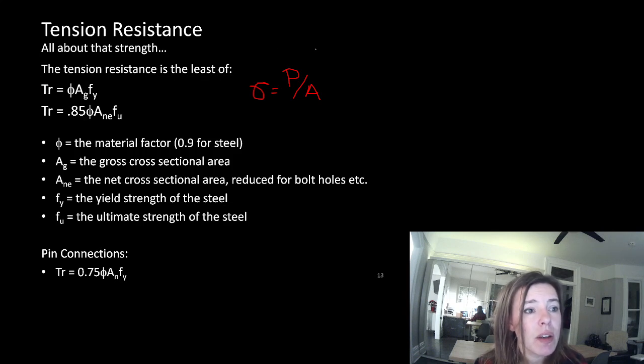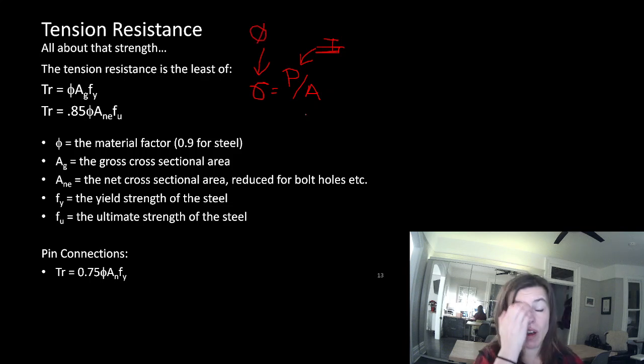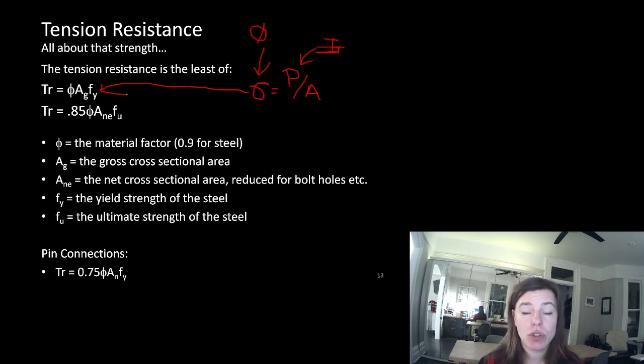TR is, we've just said, we're talking about a force that is T. We get to use the subscript R because we are talking about this having a reduction factor on it. So remember, when we talk about a reduction factor being applied, we get to start using the subscript R. At stress, we know we're a little bit lazy writing Greek symbols, so when we're talking about our yield stress or our upper bound, we'll use the term Fy.